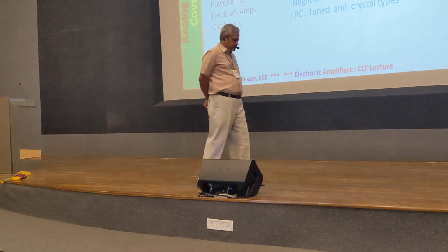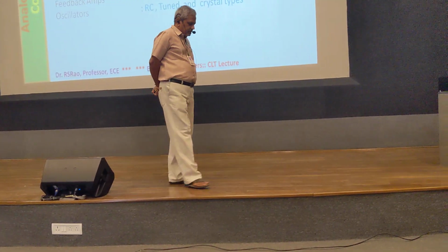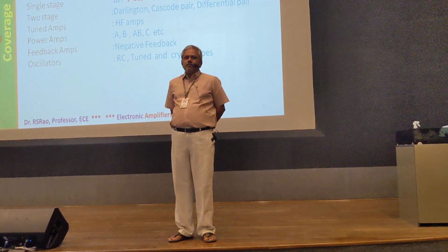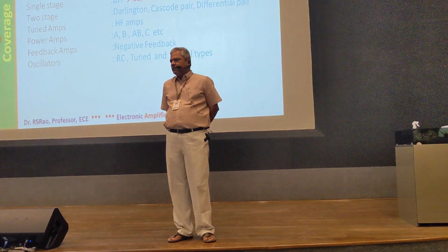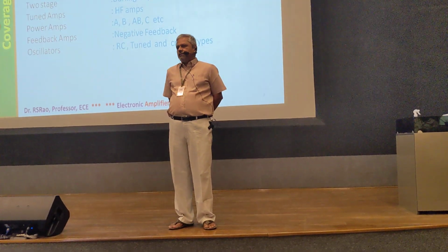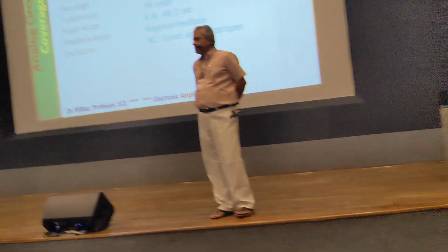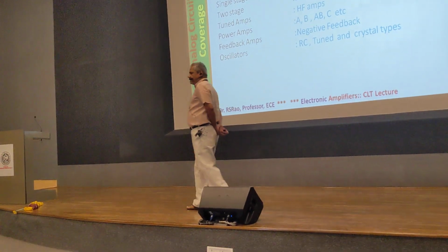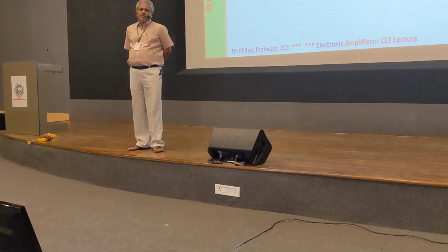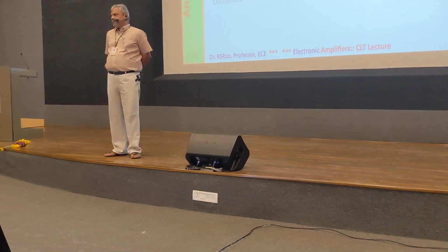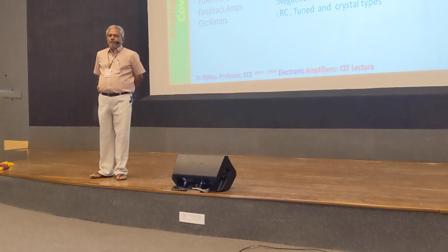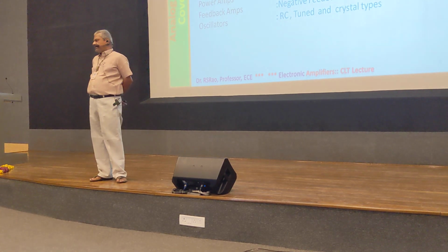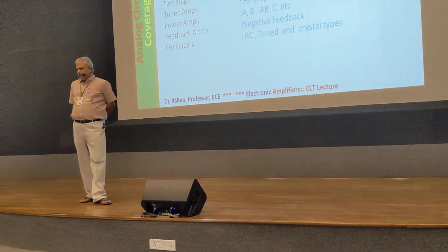Their functioning is like this. It takes two inputs. First subtraction is performed: the inputs are subtracted from one another. The resultant is amplified. So first differencing, subtraction, and then amplification. So differencing and amplification are the functioning. These two terms describe the functioning of the differential pair.